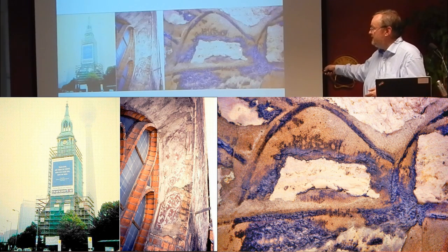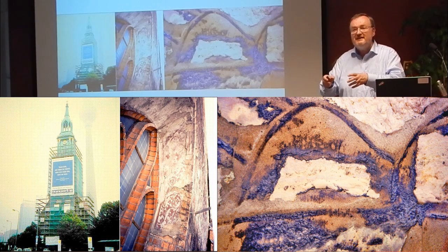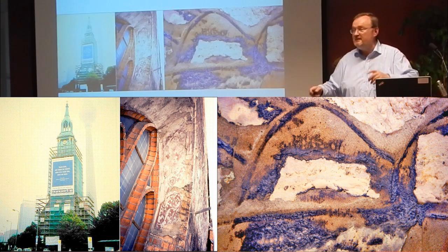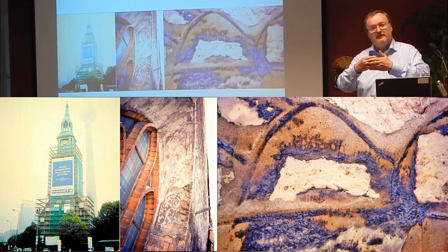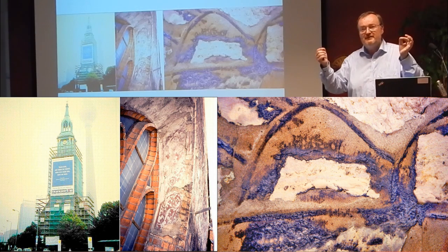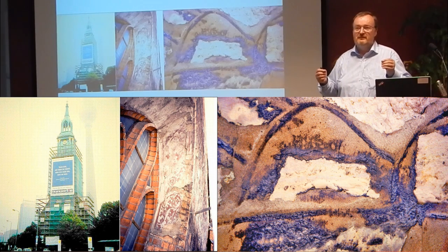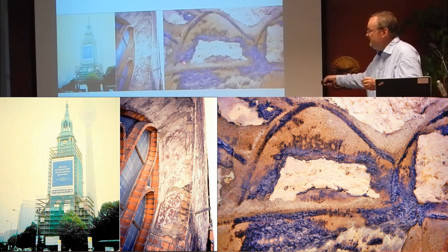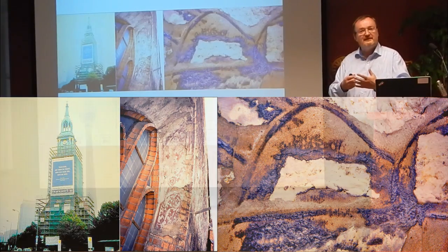Again, we could manage to repair only at certain points where there is a need, and in the rest we have open holes between the stone and the mortar. We filled only a little joint with lime mortar, because it can do this work very easily with very little work. And so the whole thing gets a new function in a technical sense with very little work.